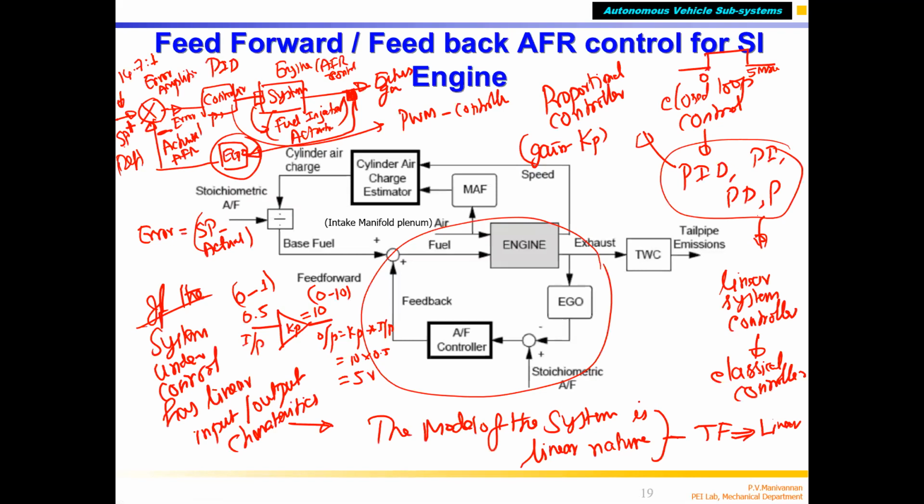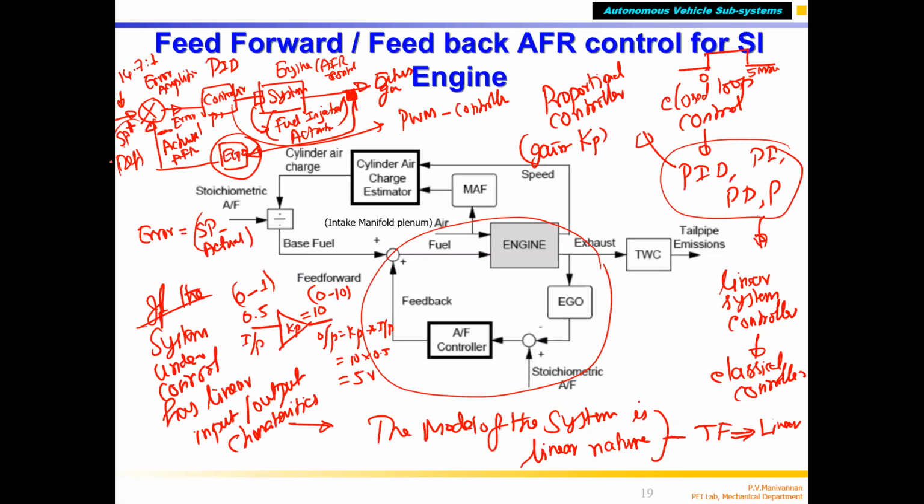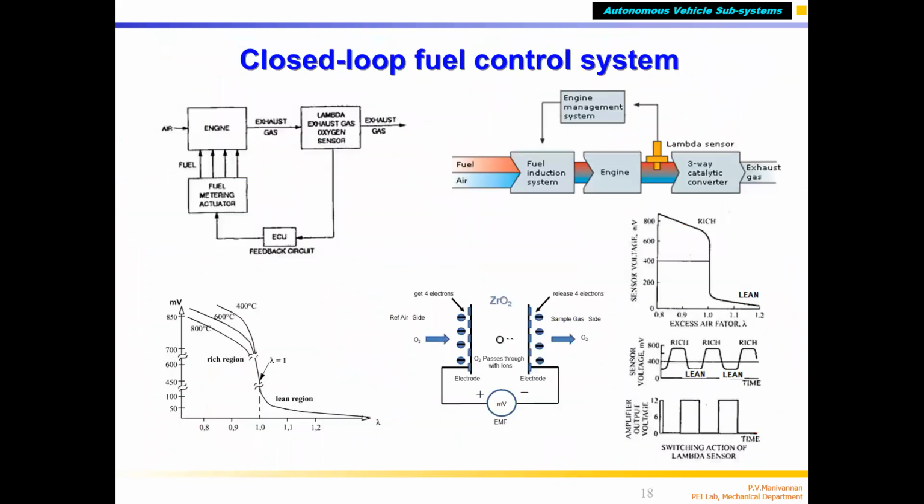Okay, we'll go ahead. Now, we are talking about the proportional controller. Depending upon the set point, you are going to vary the air-fuel ratio. You want your engine to run at 12 to 1 if you want to accelerate. This is a rich air-fuel ratio. Generally, depending upon the driving condition, it is called drivability. In engines or vehicles, it is called drivability.